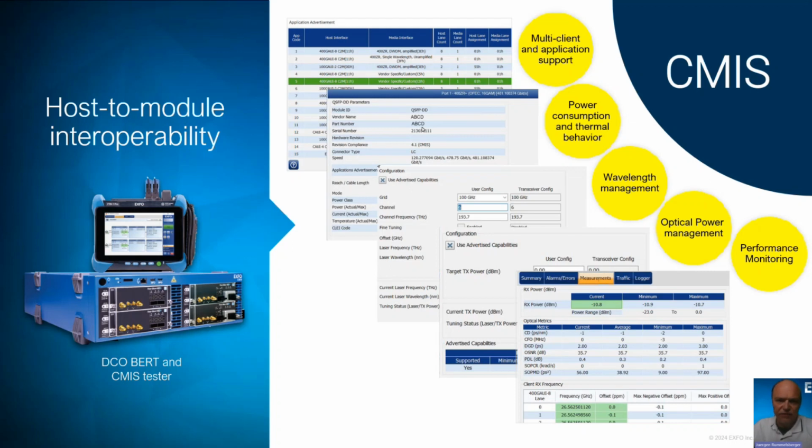So we have first the FDD, the detected degrade of the forward error correction, and also the FED, the excessive degrade of the forward error correction here. So this link degradation is the monitoring on the media side or on the line side of the pre-FEC BER, and this is done over a performance monitoring interval.